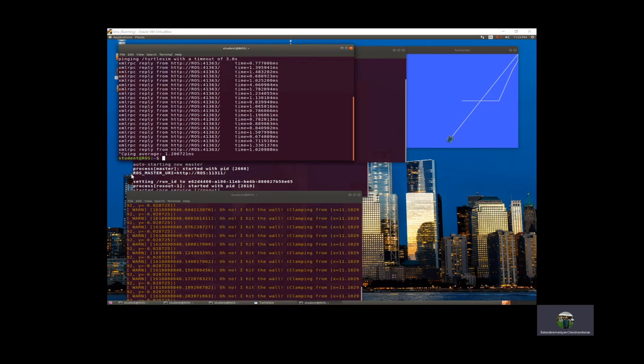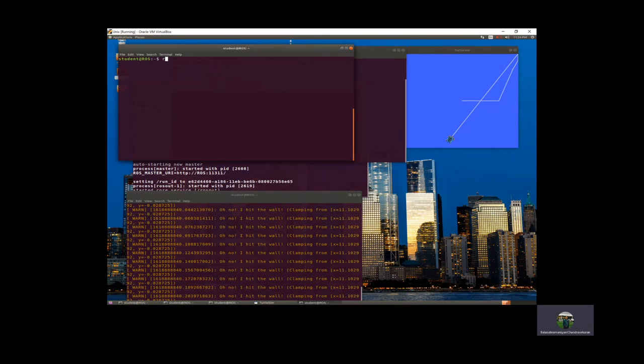Now, ROS basically uses a master, and then it communicates with client nodes. Now, sometimes it's necessary for you to have a graphical representation, because you're having so many nodes in the system. So I'm going to clear the screen. To represent the relationship between all these nodes, you have to run what is called rqt_graph. Now rqt_graph is also, think of it like, another client node.